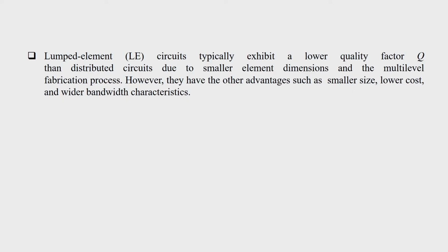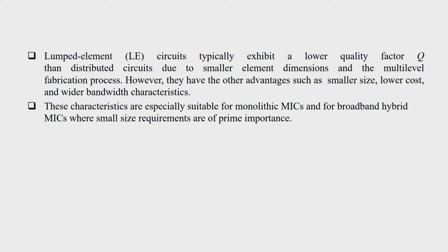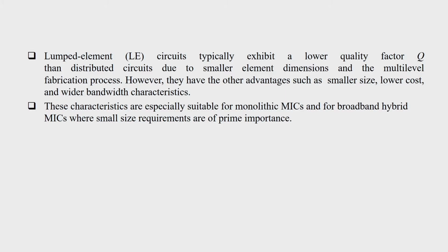However, they have other advantages such as smaller size, lower cost and wider bandwidth characteristics. So, these characteristics offered by the lumped elements are suitable for monolithic MICs and for broadband hybrid MICs, where small size requirements are of prime importance.